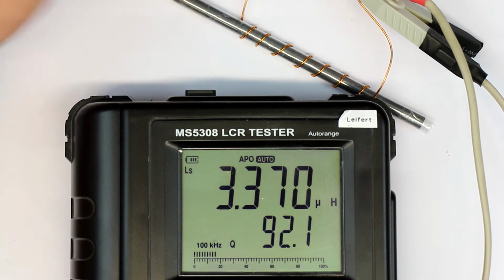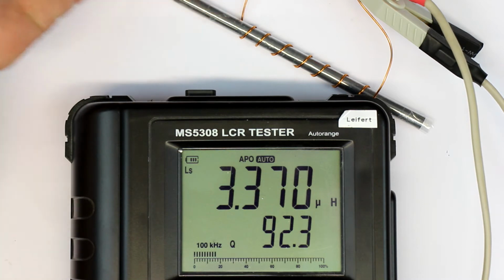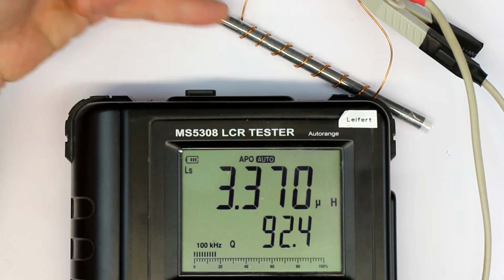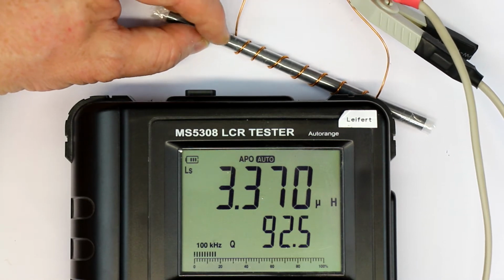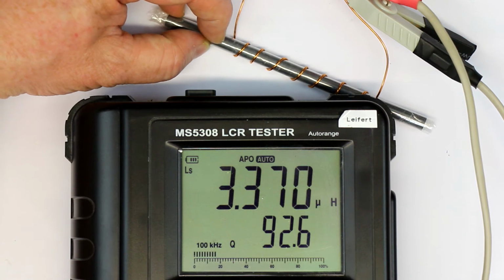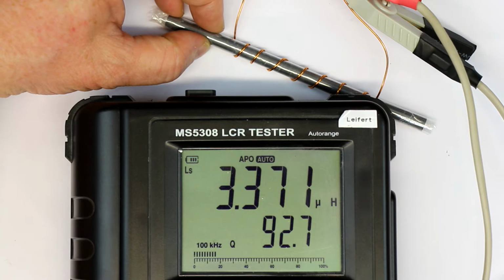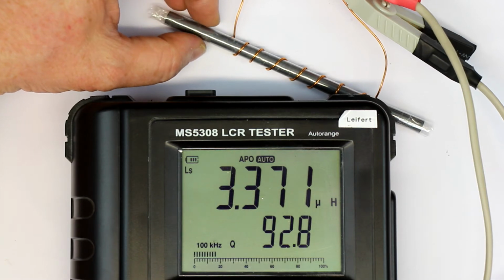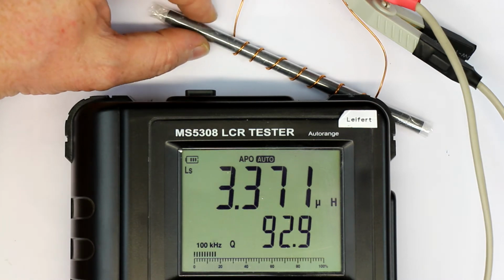That is first of all to not damage the insulation of your copper wire or of your Litz wire, because the ferrite rods can have relatively sharp edges. And the second is to minimize losses. When they are in direct contact, you could have an increase in losses.